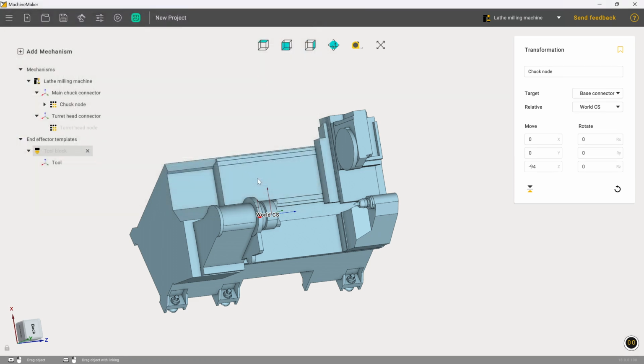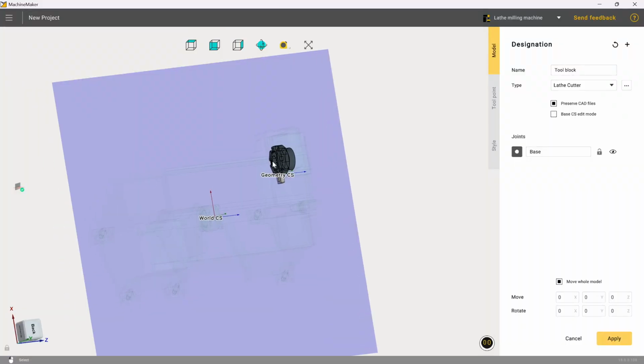I am going to grab the tool mill definition to start with. So we'll click on open for that, and we want to get these one at a time, and there is a slightly different method for adding subsequent ones, so we'll go through that in a second. First thing that we need to do is make sure that the type is correct. Now this is currently set to a lathe cutter, which is not what we're after, so I'm going to click on milling tool for this instead.